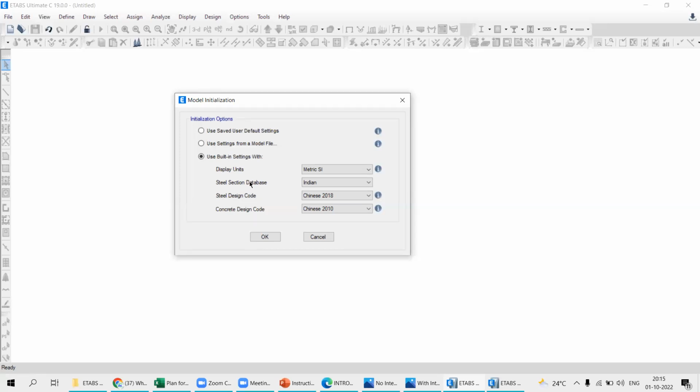All the definitions of steel sections, I section, channel section, L section, T sections. What are the different dimensions? If suppose I'm telling ISMB of 200, so all the standard sizes of ISMB 250 will be updated in the ETABS software itself. So all the sections will be updated in the software itself. You are going to define the country here, for which country you would like to consider steel section database. Now, steel design code. So based on your country, you have to decide the steel design code.